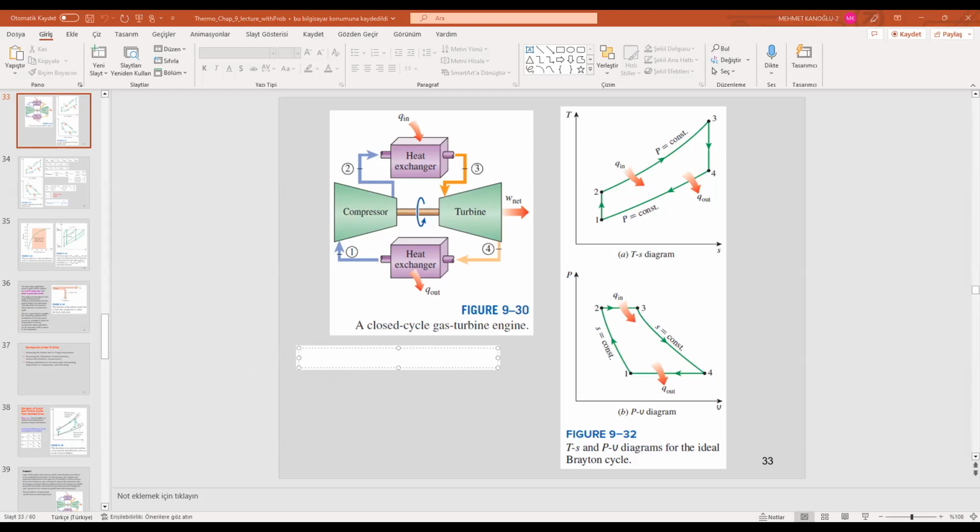So there is energy entering by mass. On a per unit mass basis, m dot h1 is entering. Anything else? There is power input entering, and energy leaving by mass from the compressor, which is m dot h2. If you solve for work in per unit mass, dividing by mass flow rate, you will get h2 minus h1. That is work in during process 1-2.